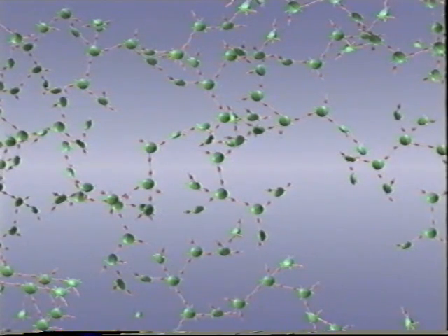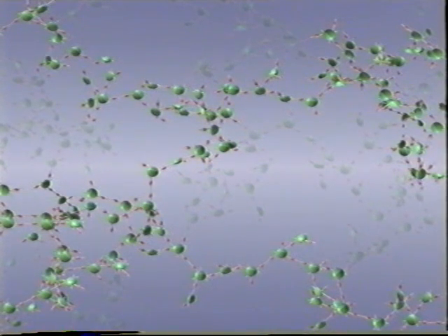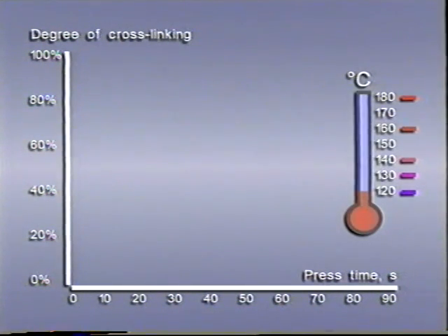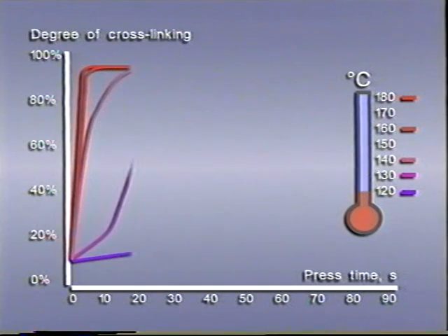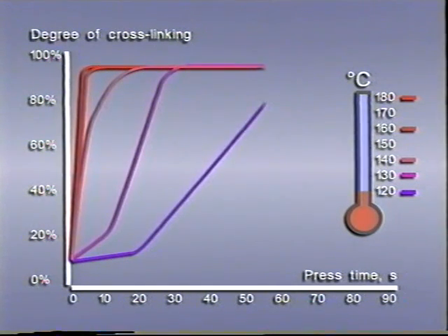At the beginning of the lamination process, long, partially cross-linked structures are created from the oligomers. This so-called gelation marks the end of the flow phase. Additional molecular combinations create a three-dimensional network which gives the material its desired surface characteristics. Eventually, the chemical reaction comes to a halt. Usually, the reaction rate during lamination depends upon the temperature. Press temperatures above 130 degrees centigrade ensure a faster hardening process and a shorter flow phase.